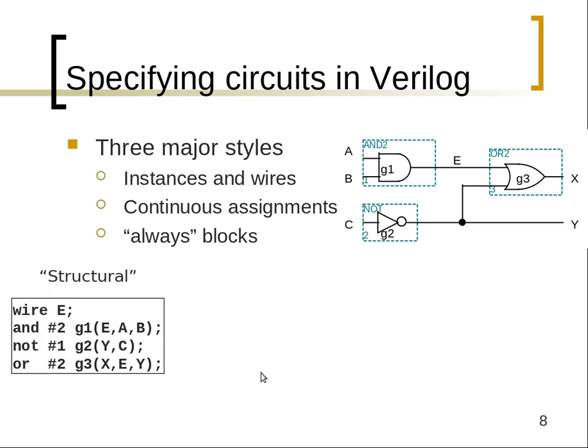By the way, what's the total gate delay of this circuit? What is the longest path? Through the OR. Right, so we got to go through the AND, which costs 2, and the OR, which costs 2, so the total gate delay is 4. This NOT happens in parallel to the AND, so that NOT finishes saturating even before the AND finishes saturating. So the NOT happens in parallel.